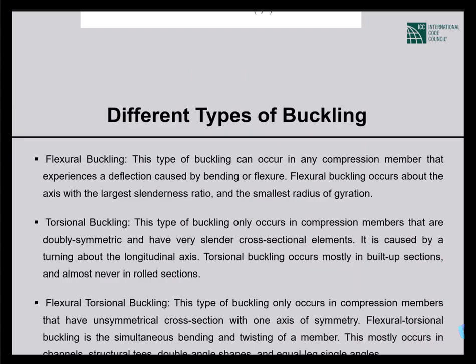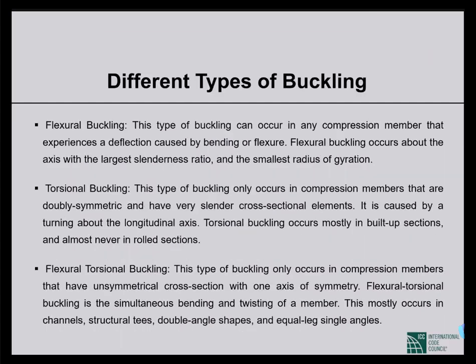Now, as I was mentioning, buckling may be induced not only by compression, but also by flexure, because for flexure there will be compressive stresses, and the compressive stresses may induce buckling. For torsion, you may be surprised that torsion causes shear, right?